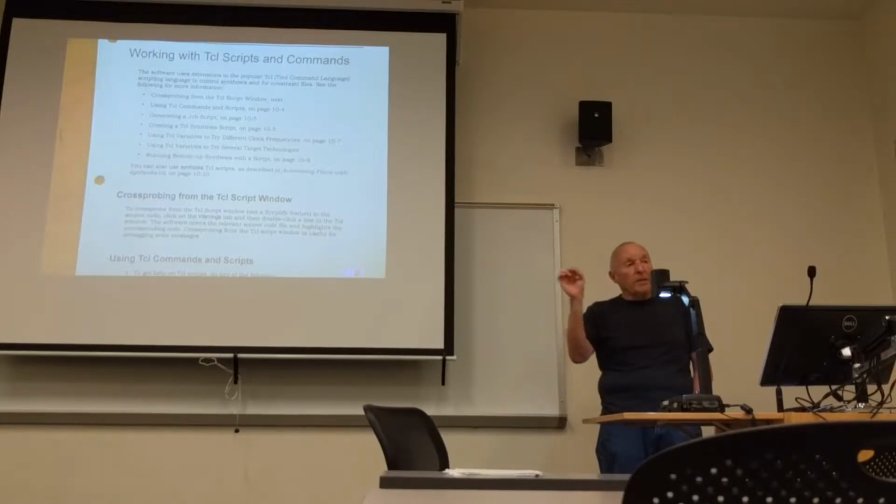So rather than you typing in every individual command to do a synthesis, you will put all those commands into a script file. And then from a command line, all you do is you type in the name of the script, and there may be some parameters that you can add on that same command line. You hit return, and automatically it starts cycling through the commands in your script file.